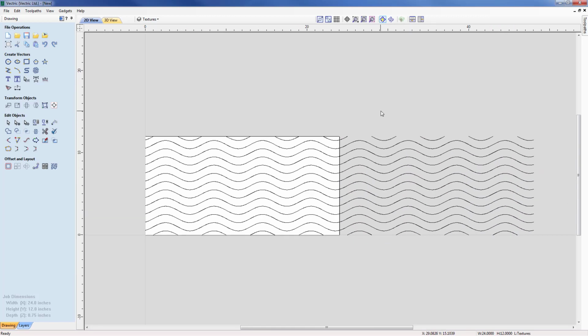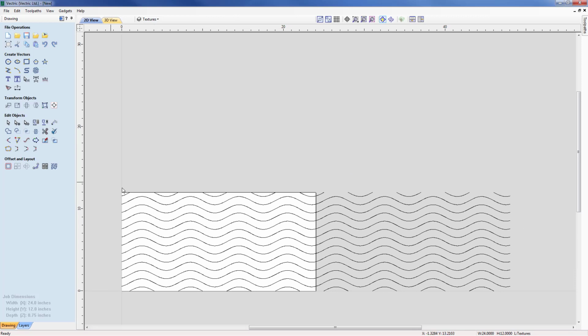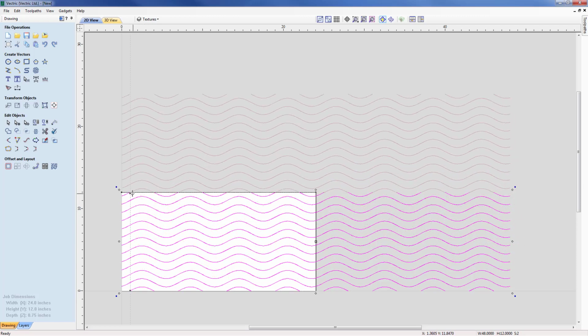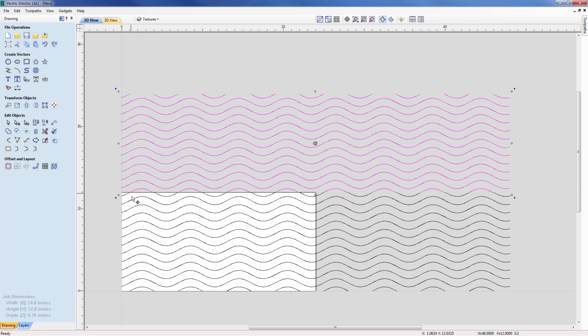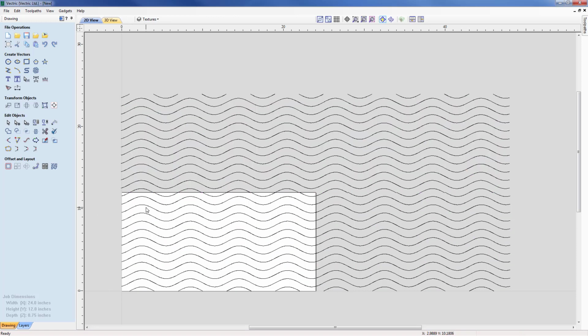And now I'm going to do the same and take both tiles and copy them up to the top. Once again, copy and paste, and I'm simply going to take the bottom point there, so I'm going to take that point there and wrap that straight onto that top position there, and we can clearly see now we have 4 tiles that look like it is one tile, so clearly that was a tileable texture.